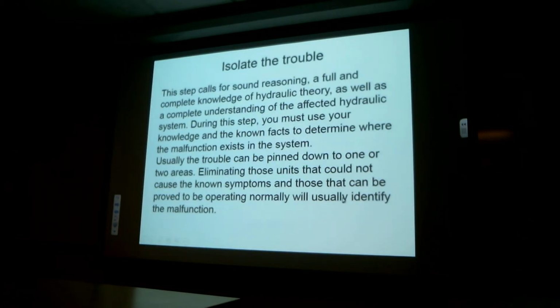Sometimes you'll see that perhaps you can't operate an actuator with the normal hydraulic power pump as a source of pressurized fluid. However, the same component can be operated maybe with a hand pump. Again, two sources of potential pressure might be used to operate the same component.